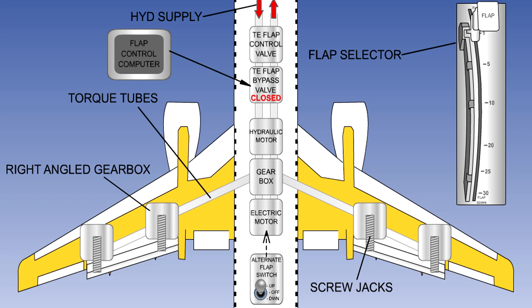Similarly, if the flaps move without the lever being moved, or they overshoot the selected position, then again the computer will shut off the hydraulic supply and lock the flaps.